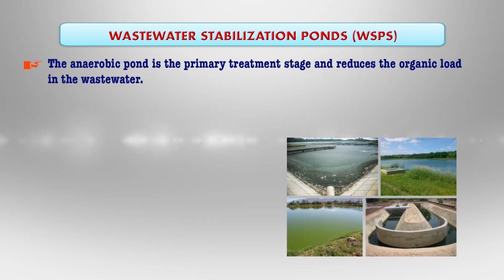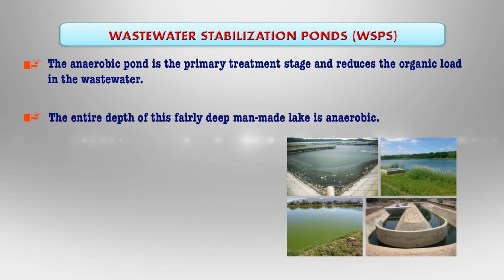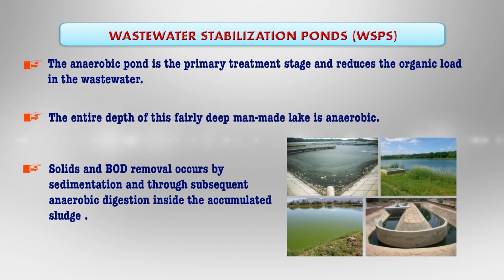The anaerobic pond is the primary treatment stage, which reduces the organic load in the wastewater. The entire depth of this man-made lake is anaerobic. Solids and BOD removal occur by sedimentation and subsequent anaerobic digestion inside the accumulated sludge.